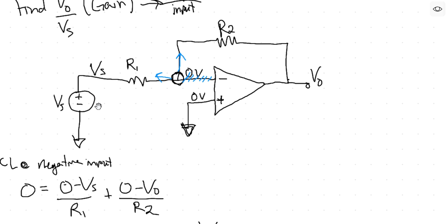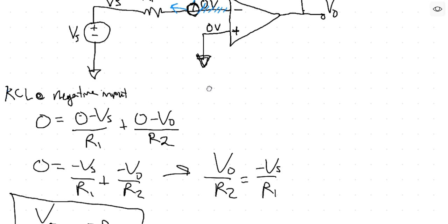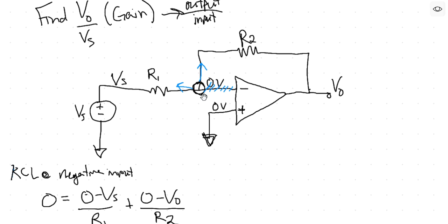Also, the circuit might not look as simple as this, even though it might boil down to a very similar gain equation. So when doing homework, and especially on tests, I would practice this using the node voltage method to determine the gain of your op-amp stages, because then you're not relying on memorization, you're actually finding it every time.